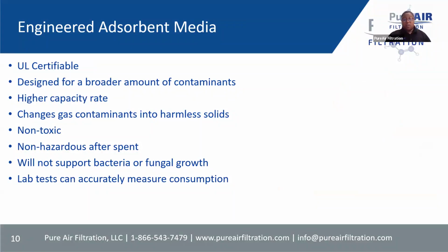Alternatively, at PureAir, we recommend our engineered adsorbent media, and this is because it is safer. So it's UL certifiable. It allows for a broader range of contaminants, and we can also target specific gases with these medias. It goes through a chemiabsorption process, which is an irreversible process, and it's more accurate. We're able to test the media life of the engineered media a little bit easier than with regular activated carbon.